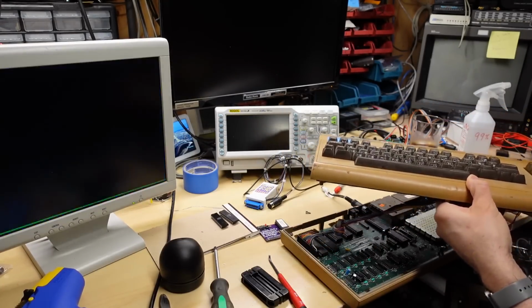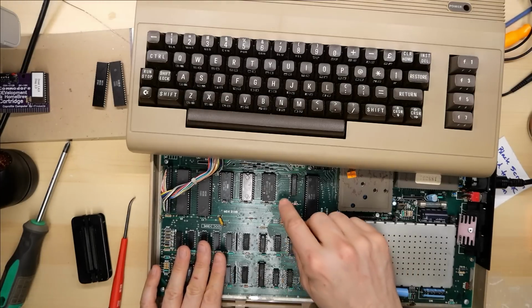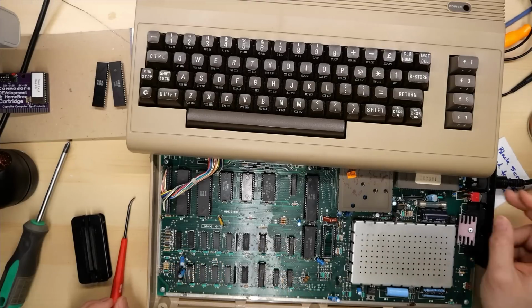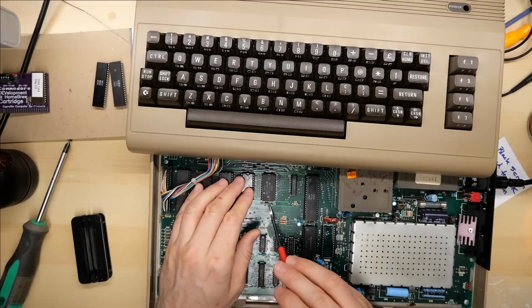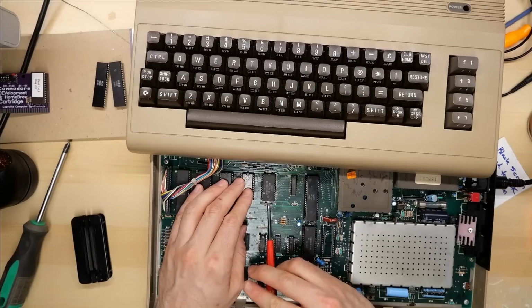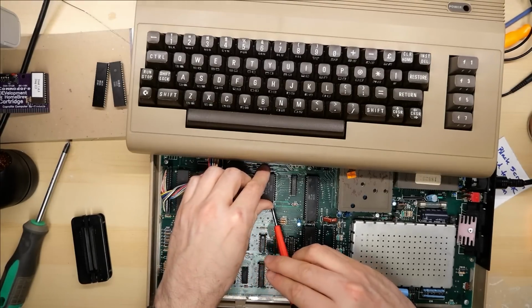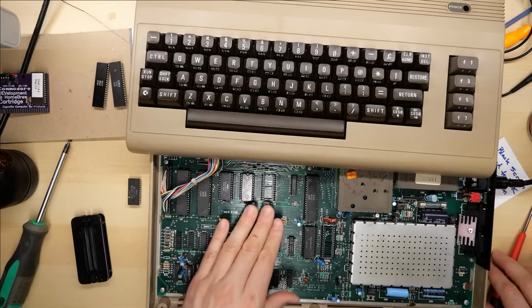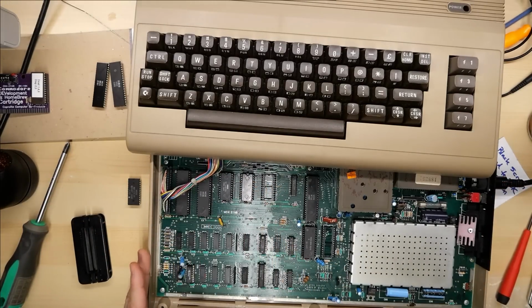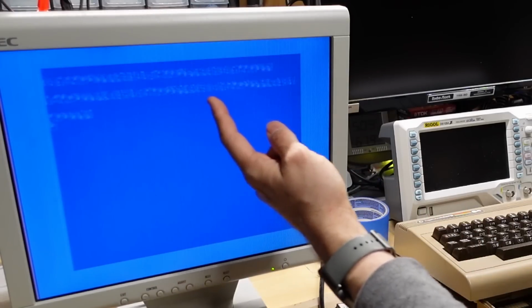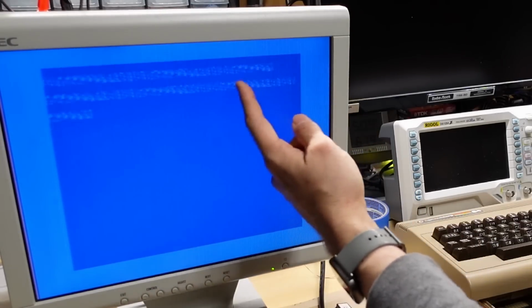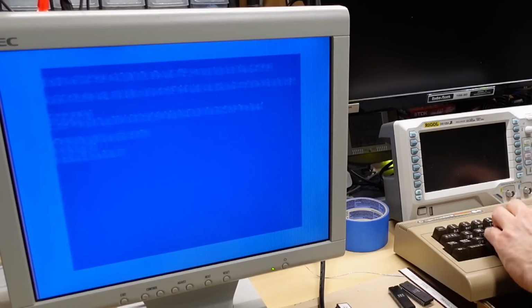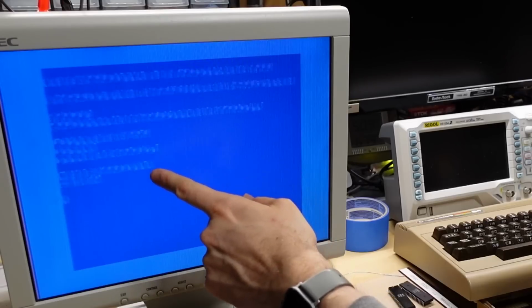So immediately when I saw this problem, I thought that maybe it was the character generator. I did test this on my ZIF64, but on that machine, I didn't really give it much of a test. I just turned on the machine to make sure that there was the image, and that looks the same on this. When you just hit the regular BASIC prompt, everything looks completely fine. If I take that out and turn the computer on, you'll see what this looks like. And there it is, all the letters are missing, and notice it looks pretty similar with these lines. It's not exactly the same, but it's like that. But if I type, every single character looks the same. So that's why I'm thinking that it's the character generator.